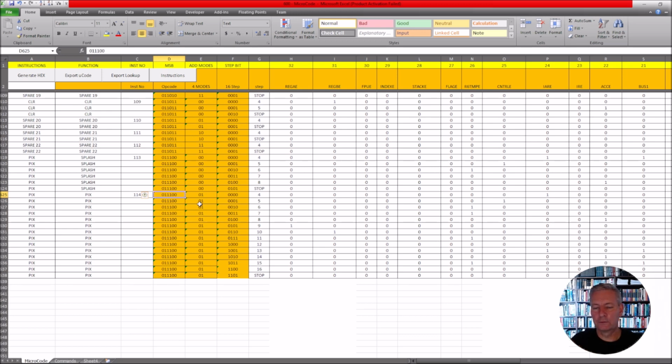And once it's put that out, it's going to have to take the value from register R0 and put that onto the bus so that value can then be saved in the little register in the graphics card. And then it's going to have to do the sets twice, so it has to set that value once in the color register in the graphics card, and then it's going to have to go to register 1 and take the position, put that onto the bus,